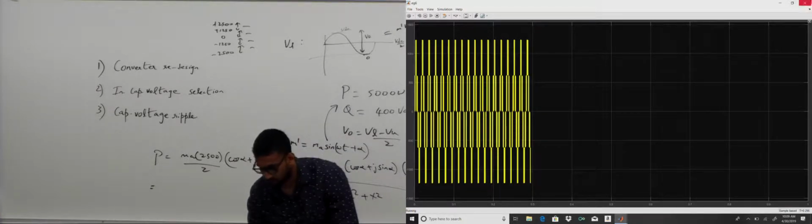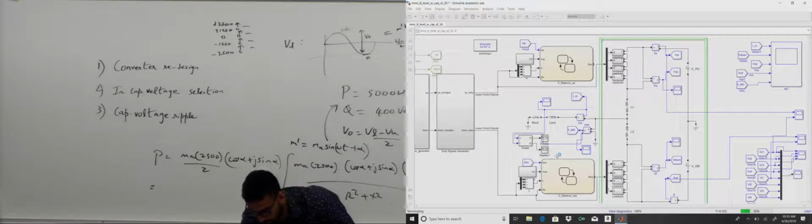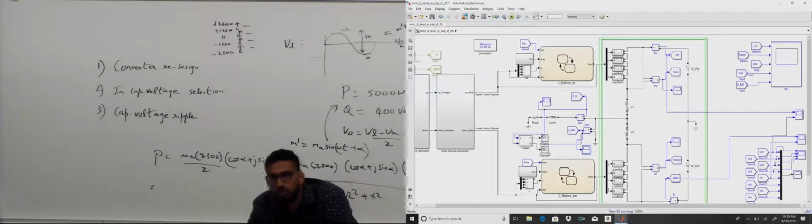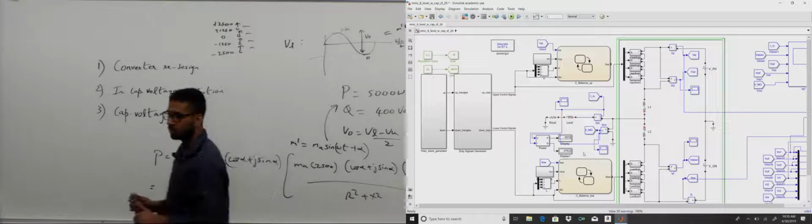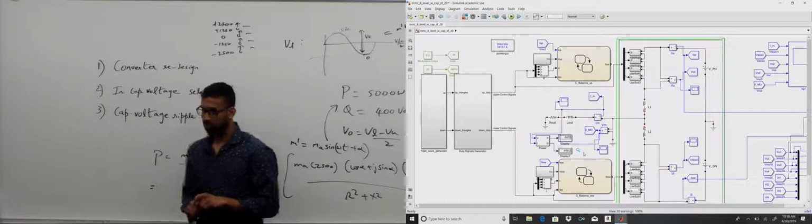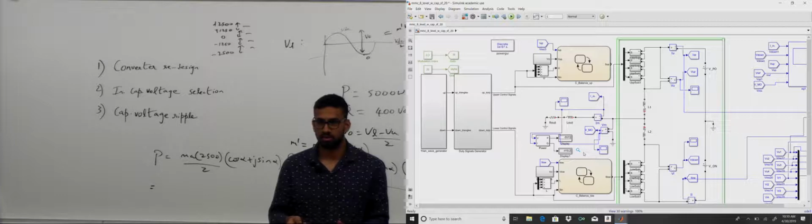So the next question is, how will you redesign this converter for a good output voltage profile and current profile? Another reason is that you get such a low voltage of 750 with MA of 0.3. You're using devices which are seeing way too high a voltage, so why waste the rating of these devices? That is the direction in which we want to redesign the converter.